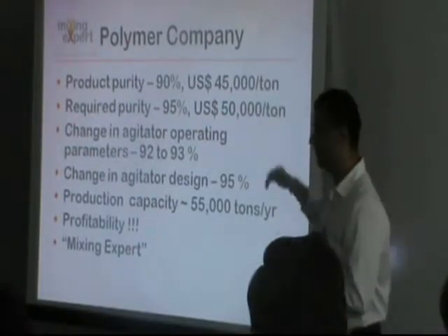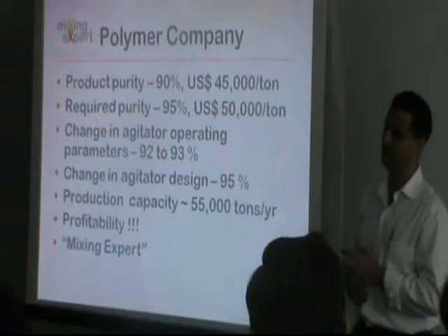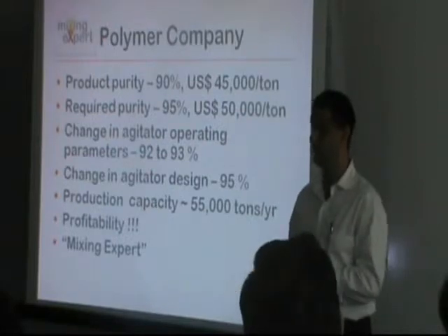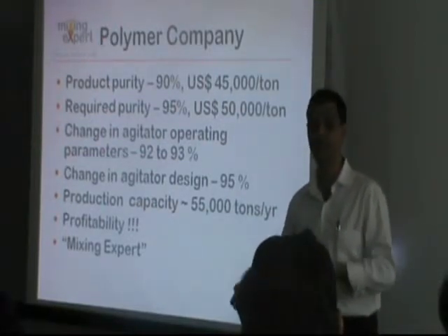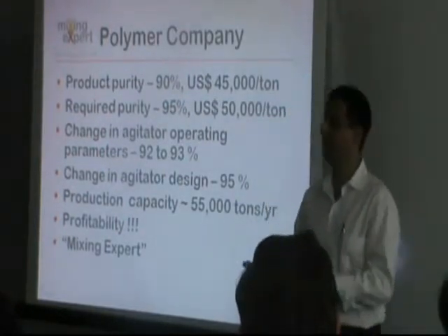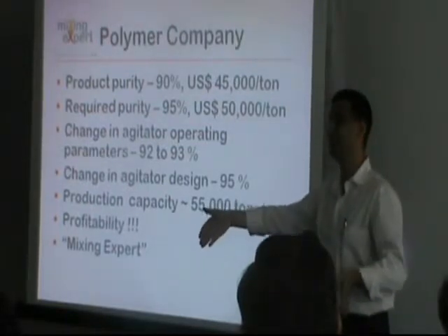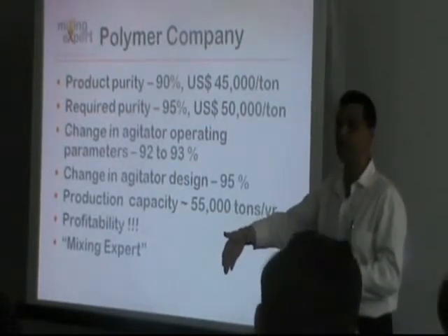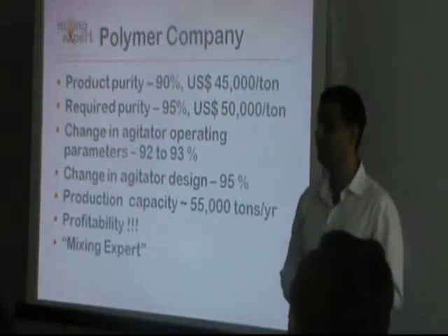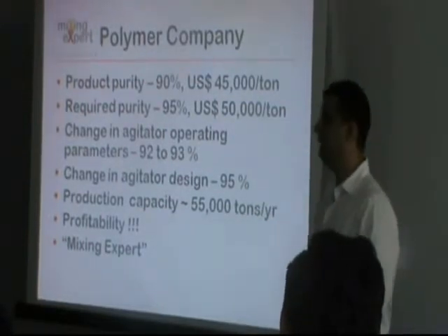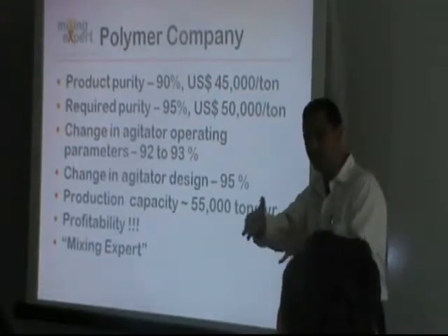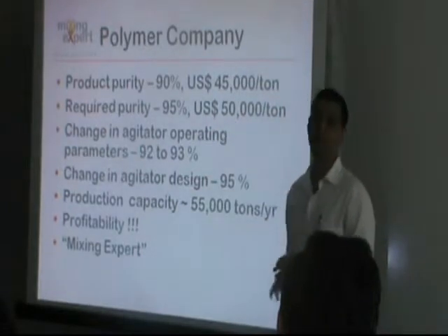The next step was the impeller diameter. Now, the polymer company was very dynamic and very flexible in its operations. With a small change in the impeller design that we proposed online, in the next one week they in-house manufactured a new impeller. The 700 mm diameter was increased to about 800 millimeters, because 50 millimeters on either side could be accommodated. Again the results were seen in the improvement in performance. With just these two improvements, from 90% they could go on to 92%.